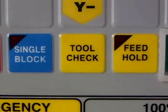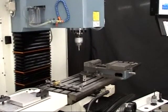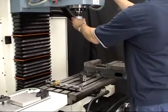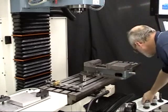Press the tool check button to retract the Z-axis to the home position. Now, just as a reminder, the actual height offset values that we're measuring for each tool using this particular method is simply the distance that the machine has to move that particular tool from the home position down to the top of the gauge block. Now, to set up all the other tools that we have to measure, we simply follow the same procedure.